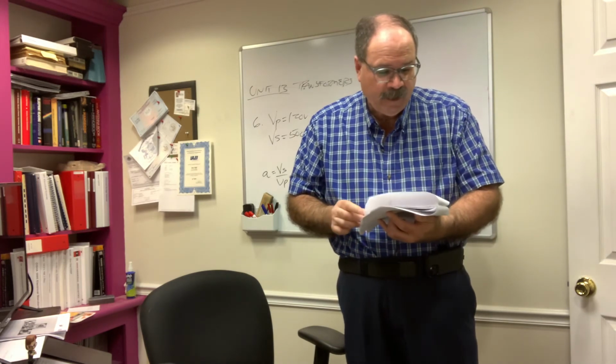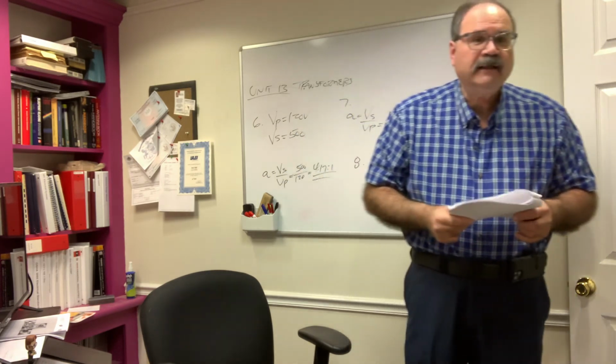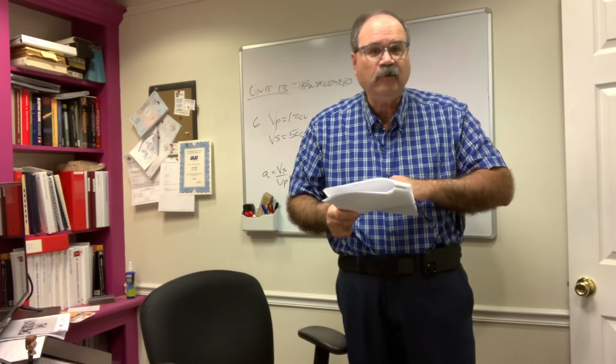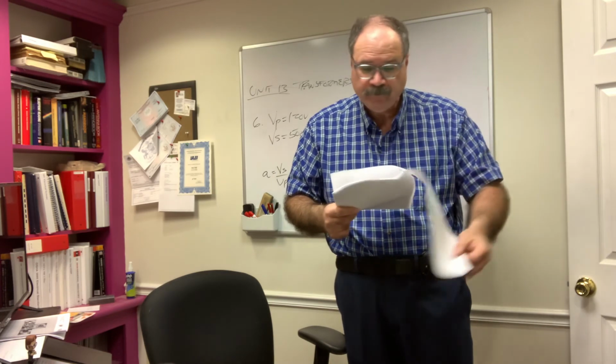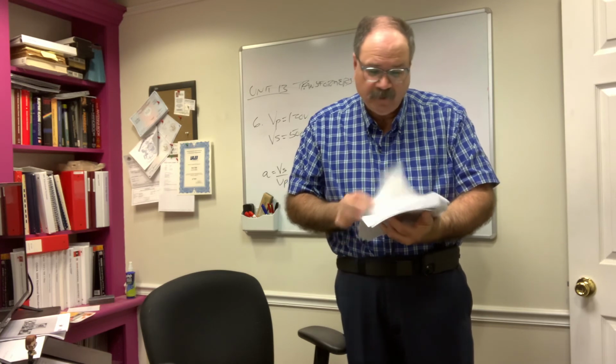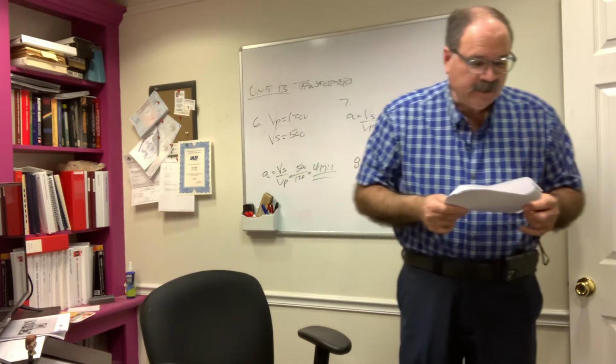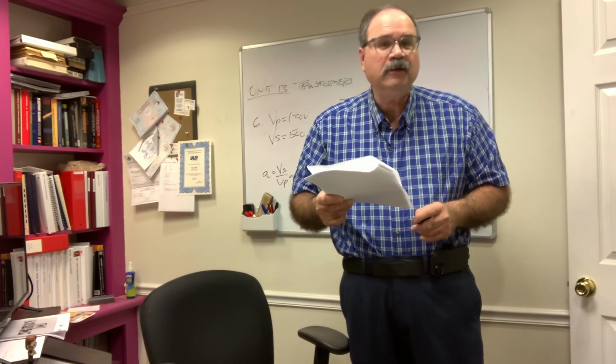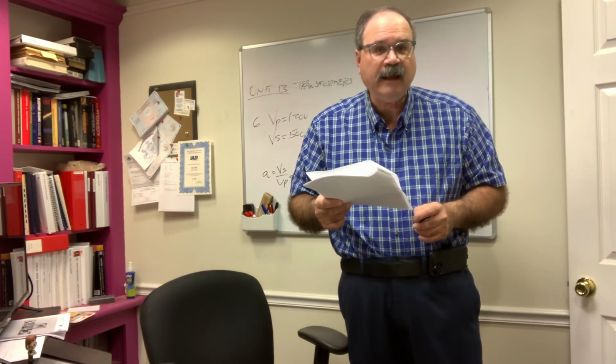Question 11. Auto transformers are an example of what's called a one-winding transformer. They don't have any electromagnetic isolation between the primary and secondary. Question 12, our last question. Almost all nameplates will list the primary voltage, secondary voltage, and what's called the power rating, the kVA rating, kilovolt amperes.